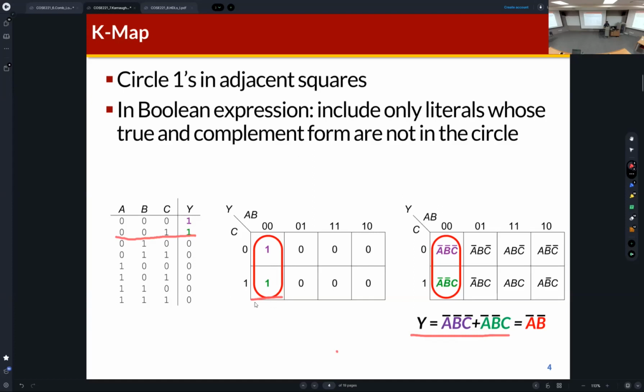So this is the example of the Karnaugh map. The truth table can be translated into a Karnaugh map like this, and you can write output values in each element of the Karnaugh map. If we can group neighboring elements and make the group big, then we can easily recognize the input signals that can make the outputs. Okay.